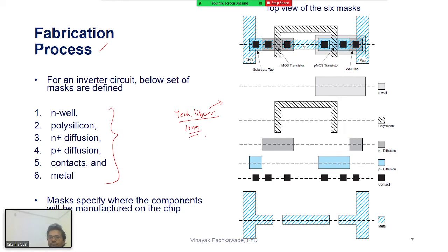Then you open the tool and the library and explore, and you say, okay, I've got these layers in my hands, and using them I want to lay out the circuit or the mask of the CMOS inverter cell. Then you create one IP of the CMOS inverter cell, then an IP of a NAND cell, NOR cell, latch, flip-flops, and you keep them in your library as a designer, as a layout engineer.